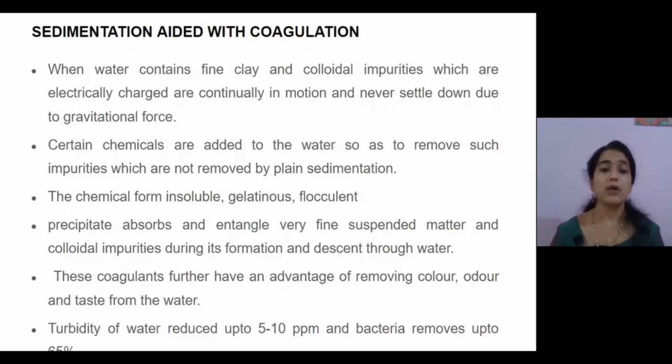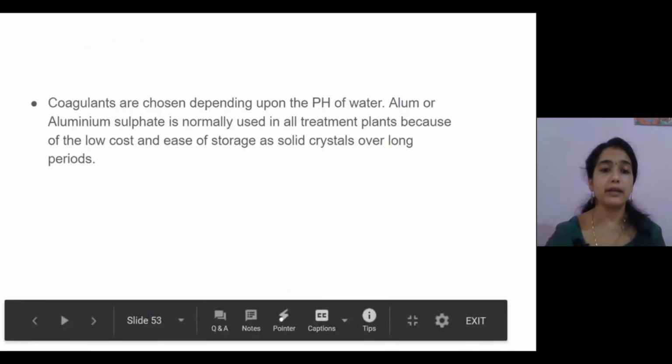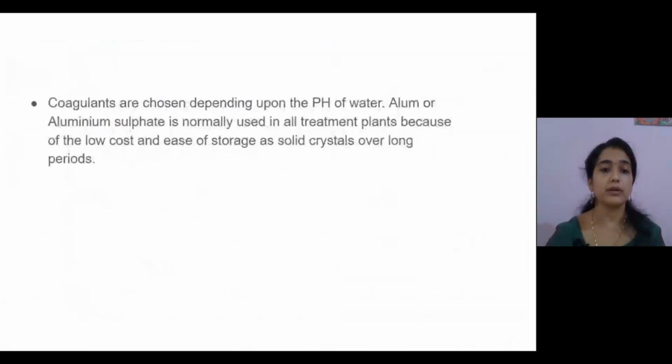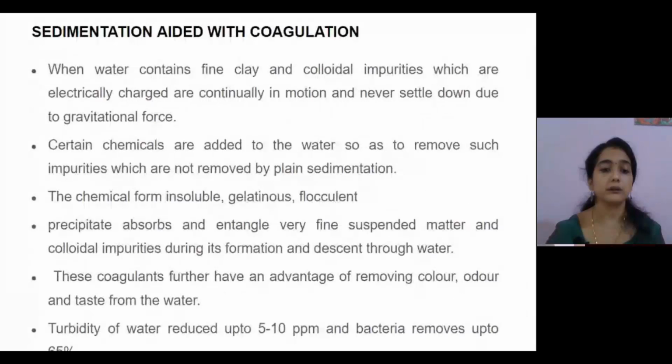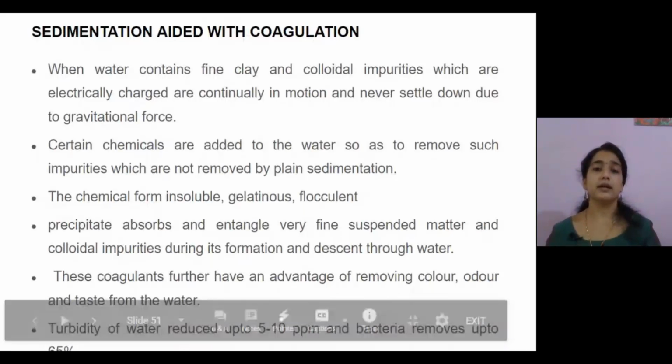These coagulants further have the advantage of removing color, odor, and taste from the water. Turbidity of water is reduced up to 5 to 10 ppm and bacteria removal is about 95 percent. And this is sedimentation aided with coagulation.